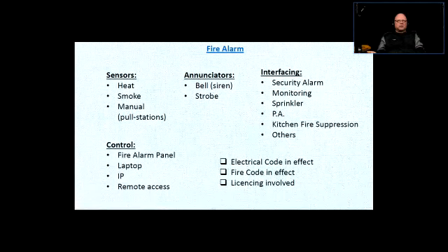The pressure is monitored by the main panel of the sprinkler system, and if the pressure keeps at whatever level it's supposed to be, then the sprinkler system is at rest. If the pressure goes down for whatever reason, then the main panel of the sprinkler system triggers. Basically, it lets the monitoring station know that the pressure has gone down.